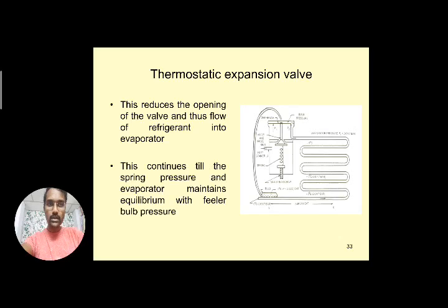This continues until the spring pressure and evaporator pressure maintain equilibrium with the feeler bulb pressure, that is, until P3 equals P1 plus P2. Until then these differences occur, and according to the load variations, the refrigerant enters in more or less quantity depending on the situation.